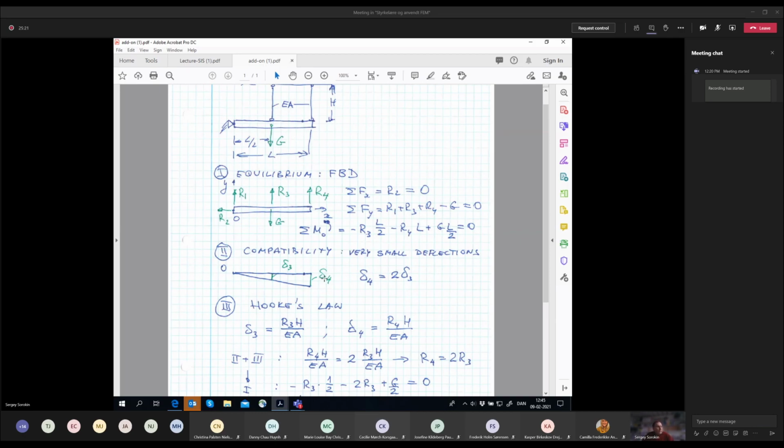Remember the Young's modulus is of order 10 power 11 pascals, and the ultimate stress is something like 10 power 8 pascals. So it's 3 orders of magnitude difference. So it means that if you have large deformation, the structure will break down. So these deflections are very small.